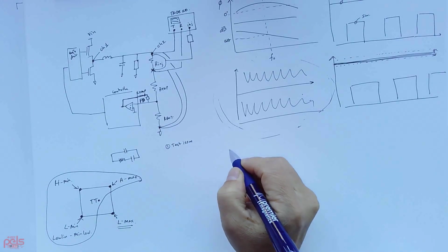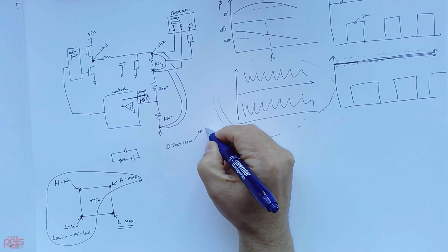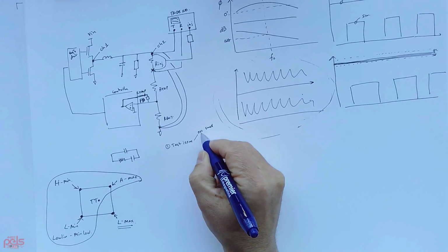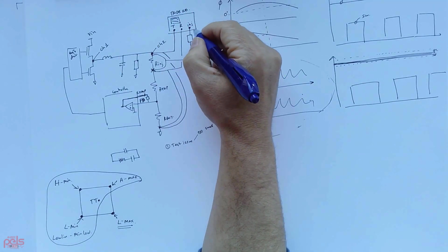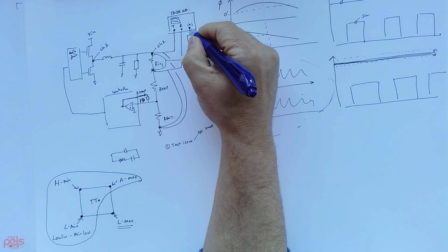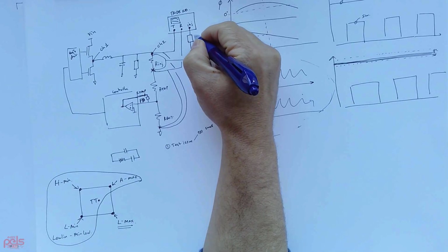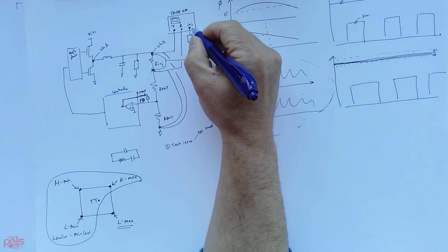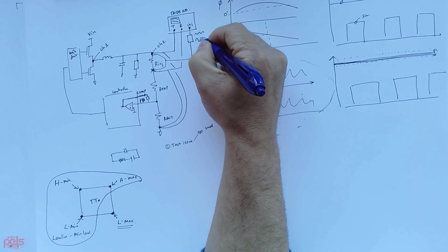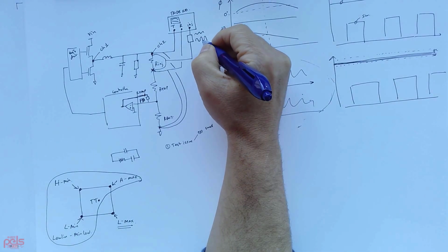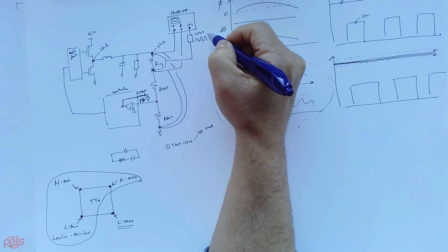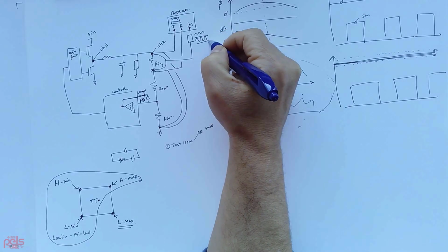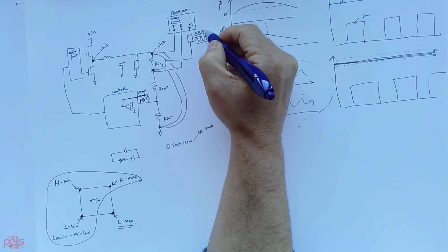Being a test issue, it could be maybe that your oscillator is too small. And when I say oscillator, I mean the injection port of the network analyzer. This port is outputting a sine wave, and you can change the amplitude of that sine wave. The network analyzer is sweeping it across frequency, right? You have a knob or a setting where you can change that amplitude.